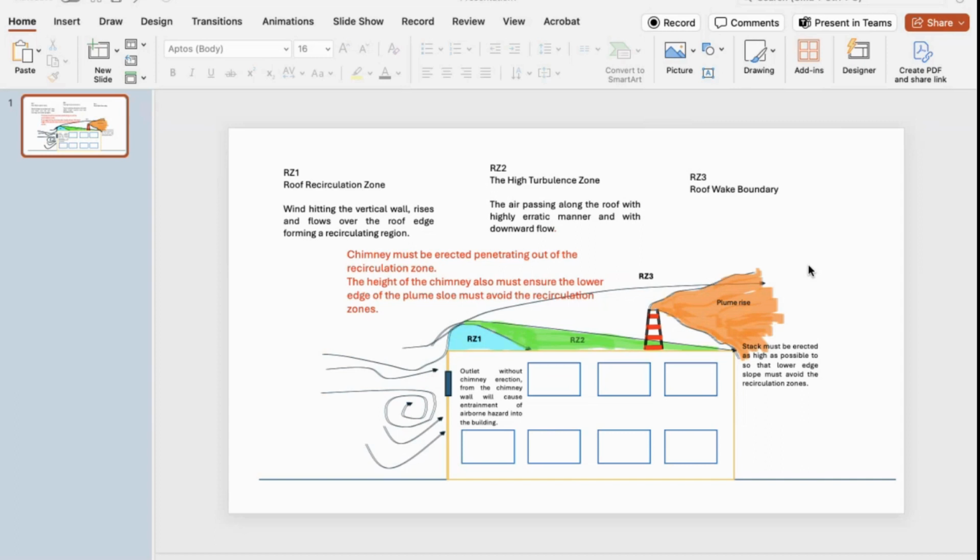A chimney needs a dispersion to take place so that the stationary source, which comes from an industrial ventilation system, does not affect the ground level concentration, which is very important to justify whether it's creating environmental impact or not. So that's why a chimney and stack is very important.